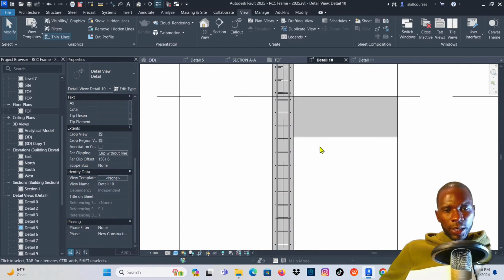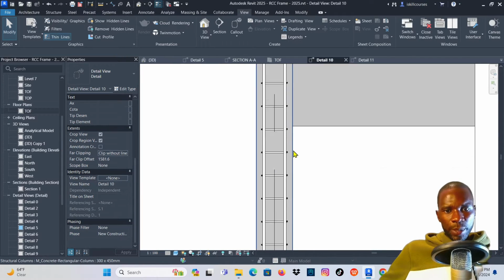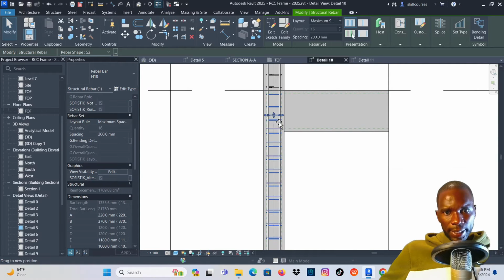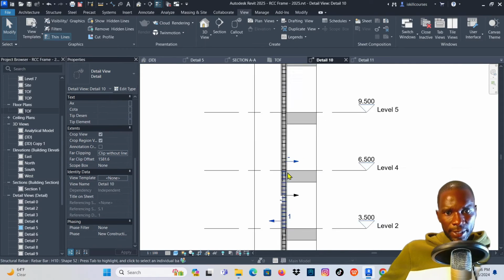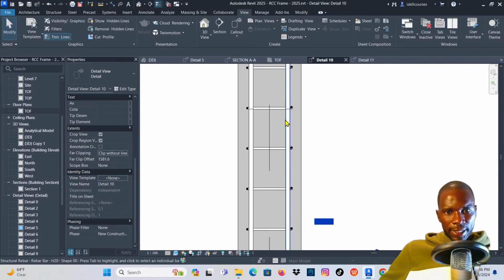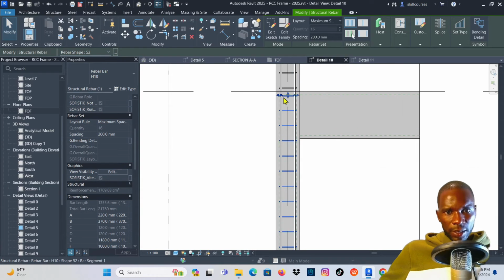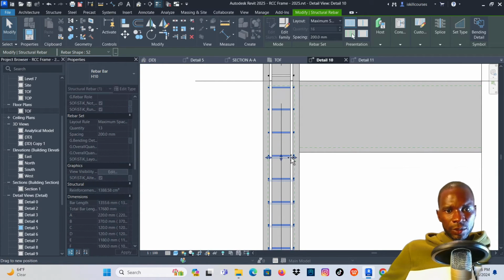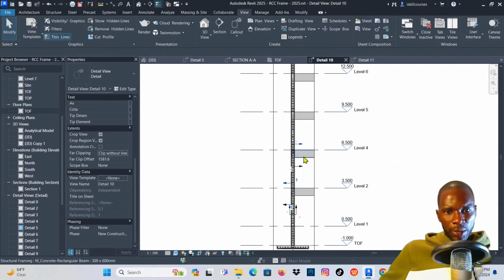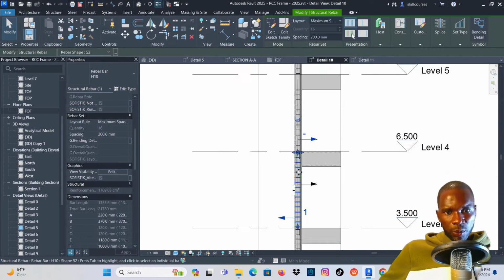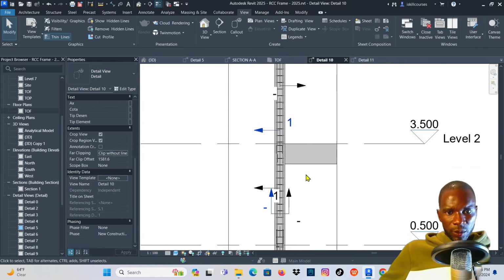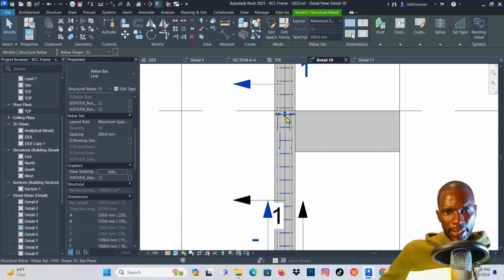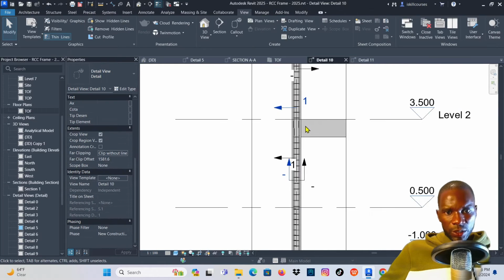Now if you don't want the stirrups to go through the beam there, you can simply make those quick edits, maybe up to somewhere here. If you want it to terminate right there, you can do that. I think practically, yes, that's what we do. Don't want these stirrups. Again, it depends on the depth of this beam, but maybe in this case, I just want the stirrups to terminate up to somewhere here. Ideally, maybe I should have even done this, then copy so that I don't have to redo this, but all the same, it's faster. I can make these quick edits if I so wish.